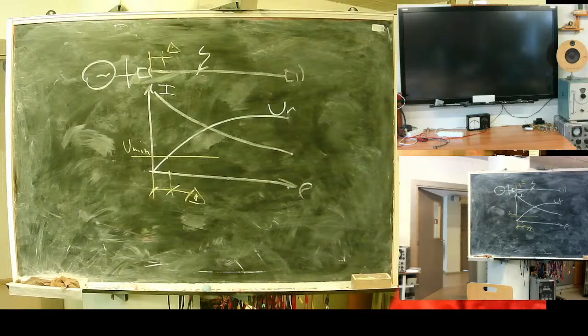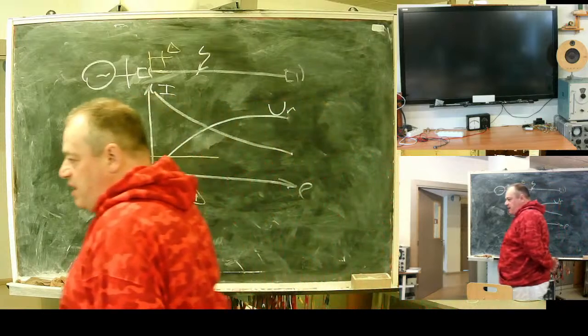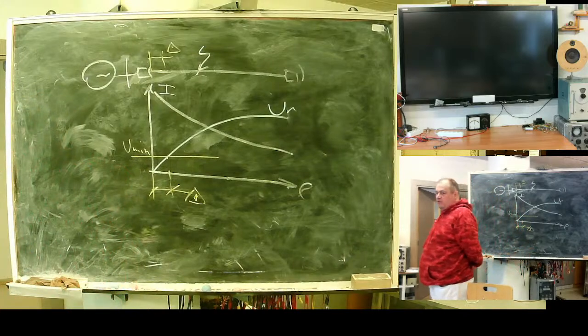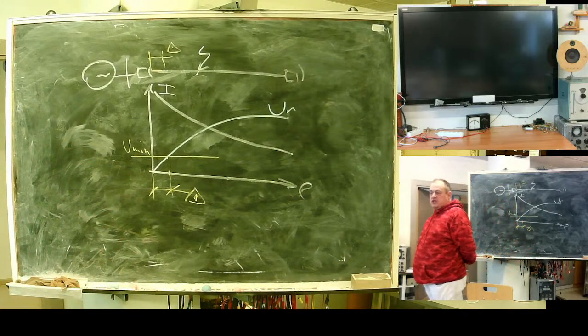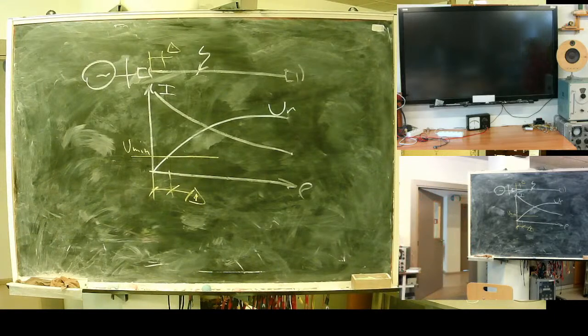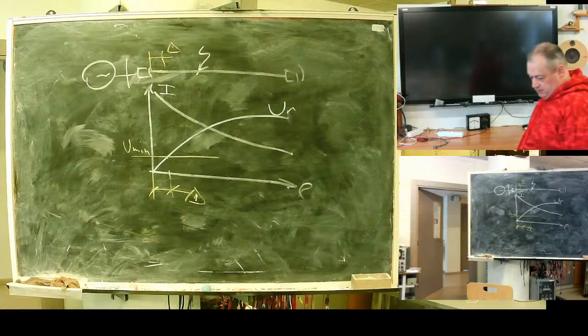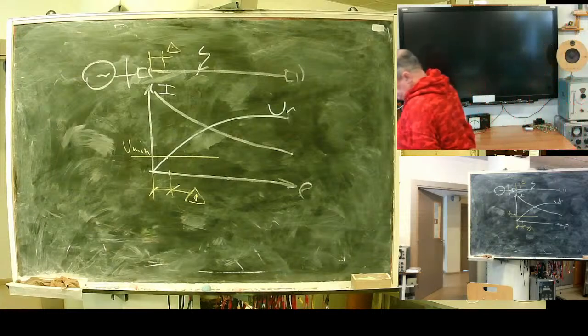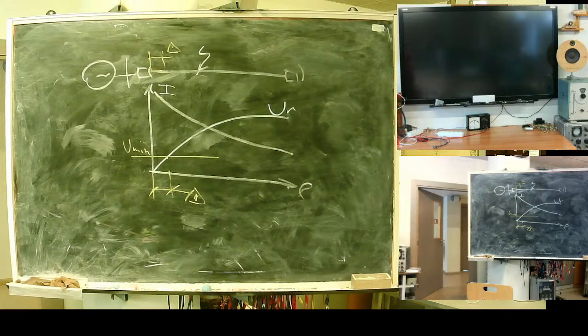Generation 3 relays, digital, had a memory for operational voltage. If voltage is below precise operation threshold, voltage from memory used to determine direction, relay becomes polarized. Not a very safe thing. Why? Why it's not safe?